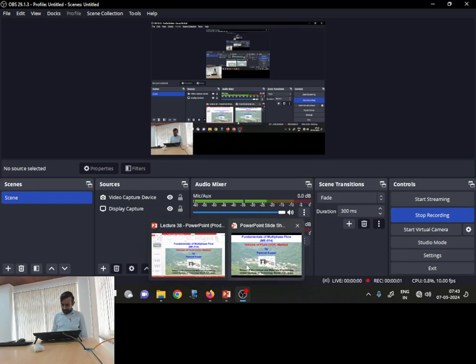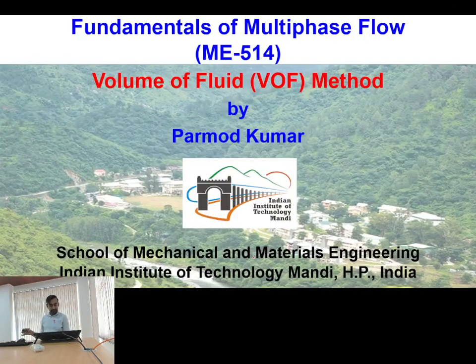Good afternoon. Now, this is lecture number 38, and already we have started discussion about volume of fluid method. So, we will try to see today in volume of fluid about the different reconstruction methods. Okay, so in volume of fluid, as I have specified earlier, there are two types of approaches. One is interface reconstruction method, and second is interface advection step.